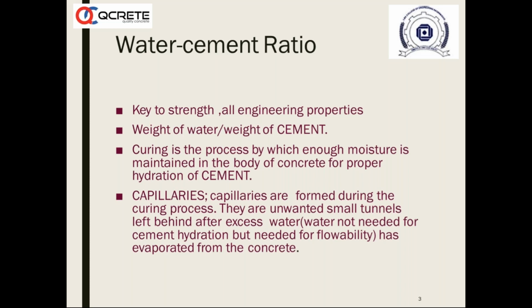That means, if we have 400 kg of cement or cementitious content in the mix, you should have 400 into 0.27, that is about 110 liters approximately. I'm talking about 110 liters of water required in the body of concrete when we are making a concrete with 400 kgs.